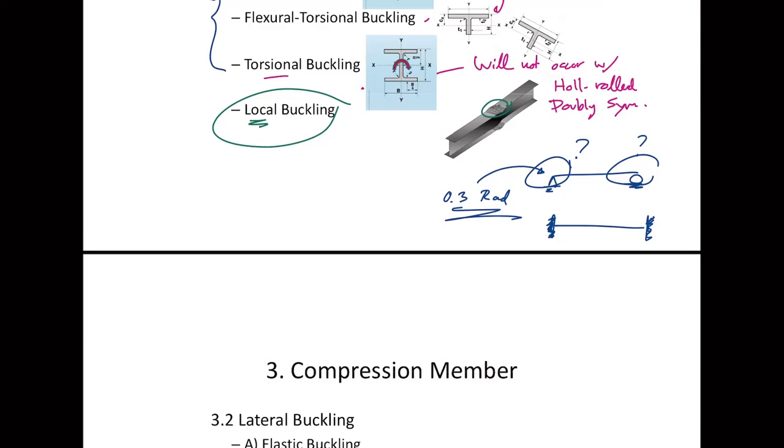Okay, that's for the pin. For the fix, I saw a paper a long time ago showing that they really could create a fix, just by adding steel plates to make the support really stiff. It's possible, but it is very expensive. So again they have details: if you connect the parts of the member where it transfers the moment, that becomes the fixed support.